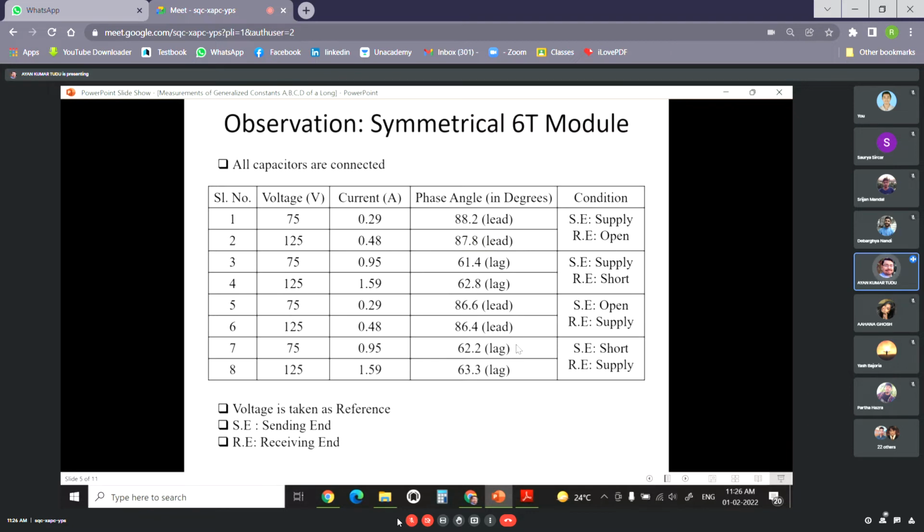We are studying power system performance also. In the first class of my power system performance course, I said that reactive power is strongly coupled with the voltage, and active power is strongly coupled with the load angle delta. So if we have to maintain the voltage at the prescribed values at all times, please remember that it is necessary to maintain the balance of reactive power in the system.